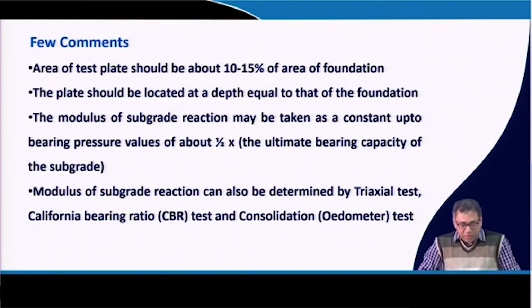Okay, so the modulus of subgrade reaction may be taken as a constant up to a bearing value of about half the ultimate bearing capacity of the subgrade. That means generally the stress-strain curve is taken as, or the k value is taken as, constant up to a stress equal to half of the bearing capacity of the subgrade soil.